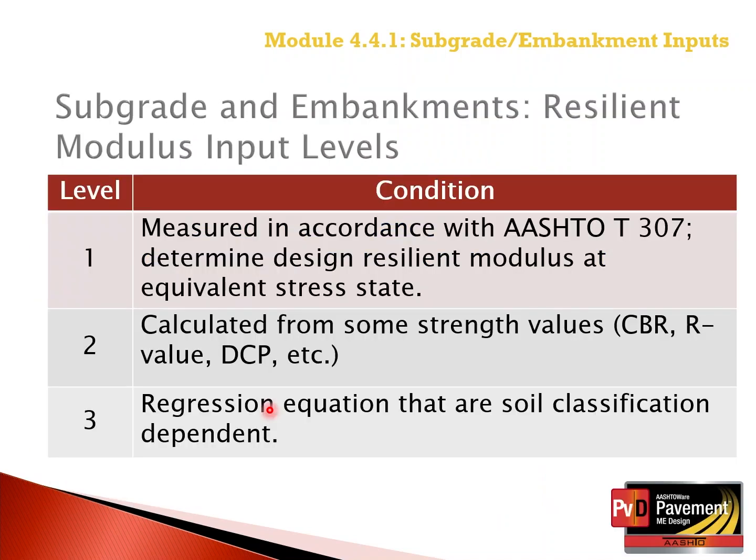Now, briefly, just remember, as a reminder, the hierarchical input levels. Input level 1, measured in accordance with AASHTO T307. Input level 2, calculated from a surrogate test. Input level 3, estimated from the soil classification, or the defaults that are soil classification dependent.